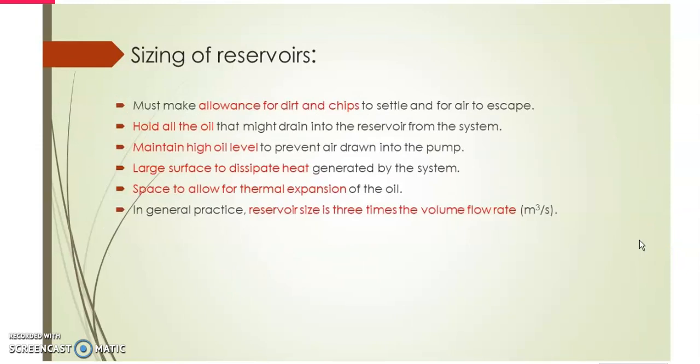For the sizing of the reservoir, the sizing is based on the following criteria. First, it must make allowance for dirt and chips to settle and for air to escape. Second, it must be able to hold the oil that might drain into the reservoir from the system.